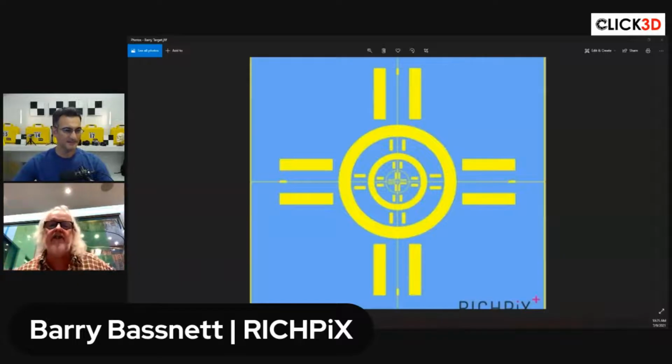Yeah. You wouldn't in photogrammetry. If you've got an oblique angle in photogrammetry, you've always got that sliding error, whether you're using a total station to measure it or you're just using your mouse and your pixel. There's always that skid mark, if you like, of eccentricity and lack of repeatability. So yeah, I haven't really found it a problem. There are, same with anything, if you go too acute. But I try to avoid those and set up so I'm shooting more perpendicular to the surface I wanted to pick up anyway.